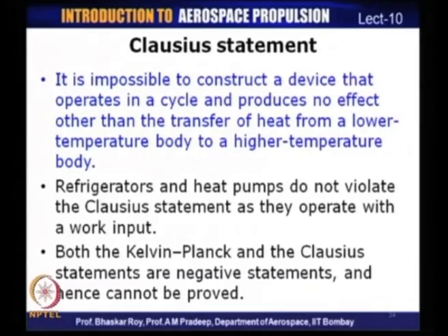So, Clausius statement is stating that you cannot transfer energy from low temperature to high temperature without a work input. That is, if you have a cycle which is continuously transferring energy from low temperature to a high temperature without work input, that is an impossibility as per the Clausius statement. So, refrigerators and heat pumps, you may wonder, probably are they violating Clausius statement? Well, they are not violating, because there is a work input required.